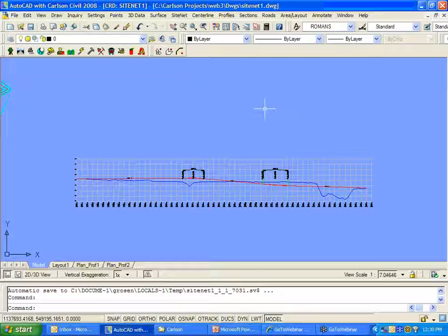Well, let's see. Some other questions revolved around the name of your title block, the drawing that you had. Can that be located on a server location? And does it have to be called profile, for example? So those can be put on a server location. You just have to have your AutoCAD path to go and find those drawings, whatever they're called, in whatever location. You just need to append that to your AutoCAD search path.